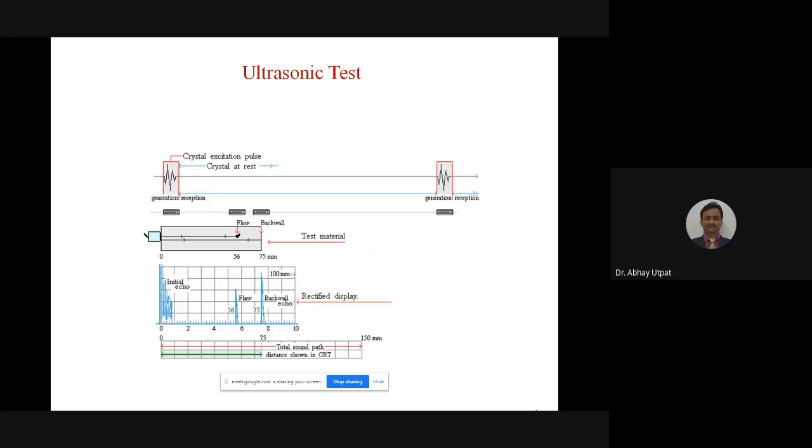And one of the most important principles of sound is sound waves reflect as soon as the medium changes. So when you are talking to the friend who is below water level, the medium changes. That's why your sound waves will not go inside the water and he or she can't listen to you. No doubt of talking from his side, because he can't talk as he is below water level. Now, this principle is used for checking the presence of cracks, blowholes in metals or alloys.